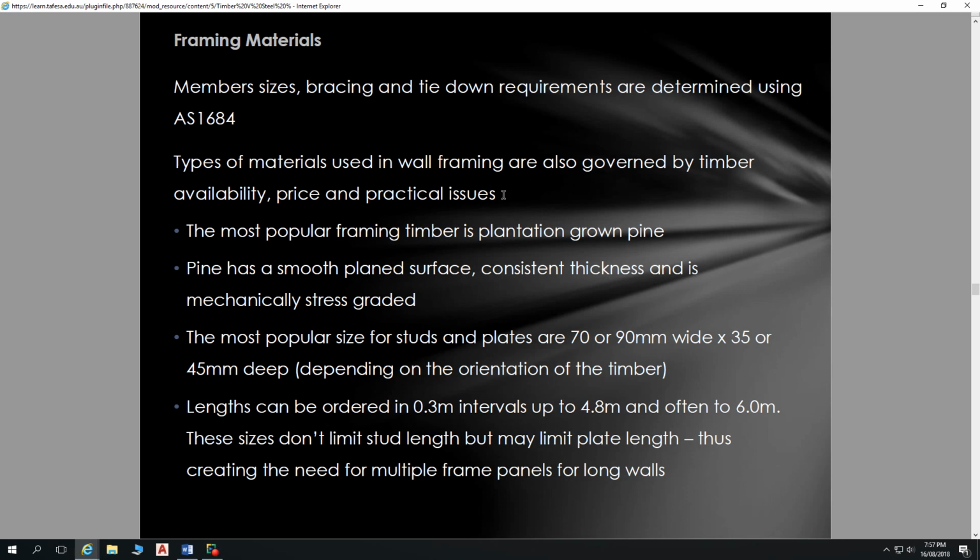I have to think about, okay, this is the size of underpurlin I need, this is my strutting spaces, etc. Work through that whole thing, and you realise, okay, I'm going to have this LVL that costs me $30 a linear metre to provide that. It's going to be cheaper going with larger 140/45s, etc., rather than 120/35s. But it's about us having to work through that.